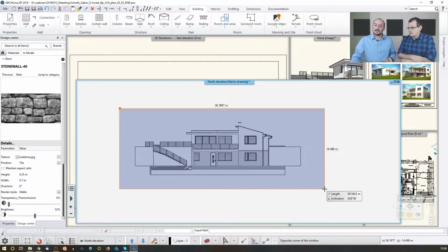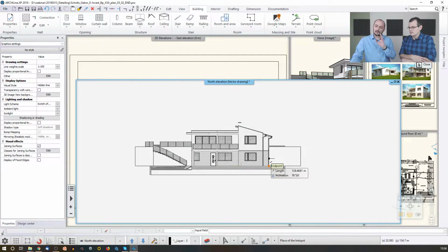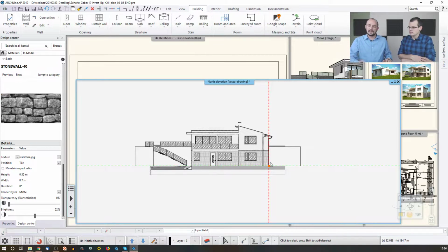So just in that case, you just select that content that is generated, and then you just Ctrl+C to copy that. You should always set up a reference point, which is this point now. It's not that important which point I clicked. It's just that it will be the pickup point of that drawing, and this is where I can set it up to place someplace else.